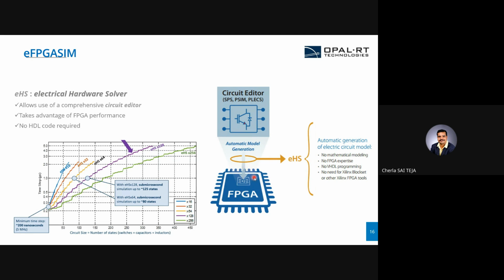Normally, if you want to do the modeling on an FPGA, one needs to have knowledge of how to write the code in VHDL, or needs to know how to use the Xilinx-based block set which is available in MATLAB Simulink. It's not straightforward because you need to have all the converter response written in differential equation based equations. The FPGA will understand only that. So we need not have knowledge of the mathematical modeling or FPGA expertise or VHDL programming.